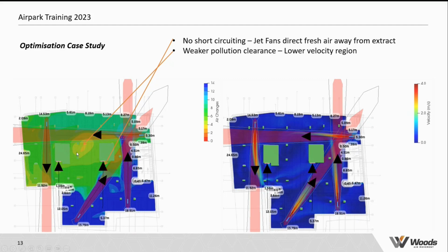So we're starting to see an area of yellow return in this middle section. So to deal with this, what we might need to do is to try and increase the velocity and the flow through here to better ventilate this region, to remove this slightly more stale area of the car park compared to the rest of the system.